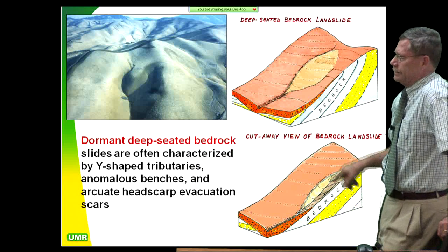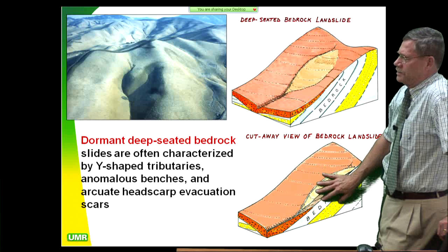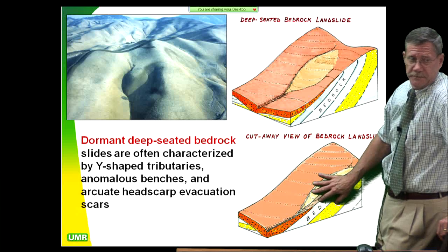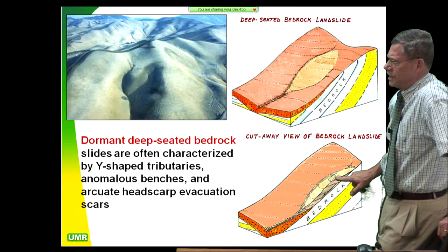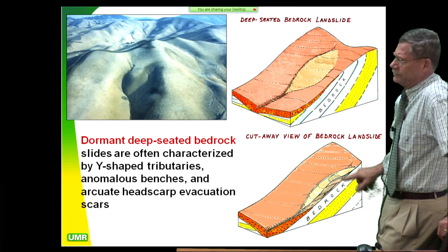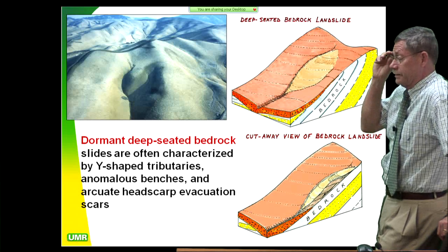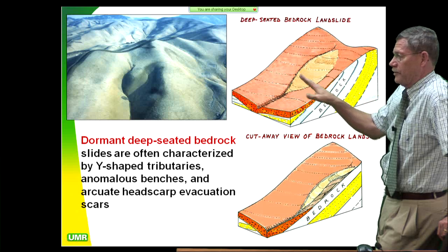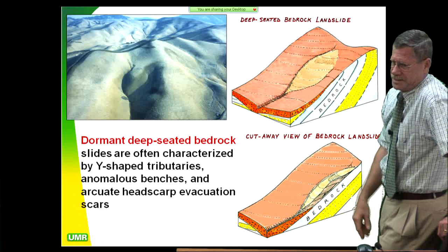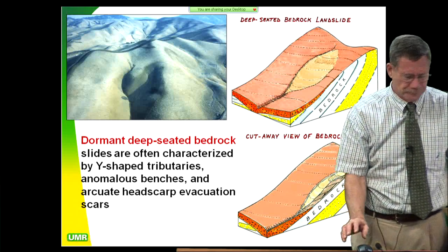Now, is that an unbuildable site? Not at all. No, that's a buildable site. The problem is you can't do a septic field or leach field on this kind of site. You're going to flush yourself down the hill real fast. So as long as you put in a sealed tank system for your water treatment, you could actually build on a place like that. In this particular case, the most expensive part of the project was the access road to get them up there. So it never got built. That was the reason, not because the house couldn't be built.